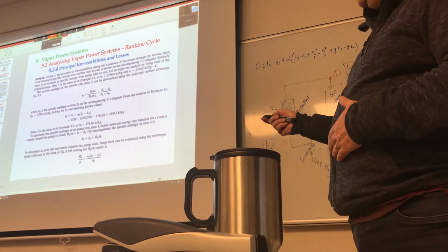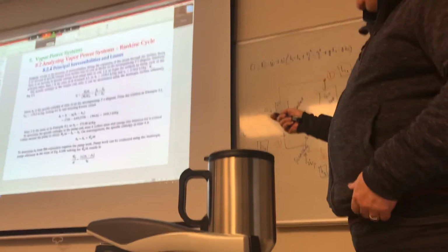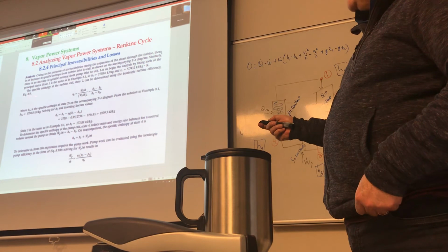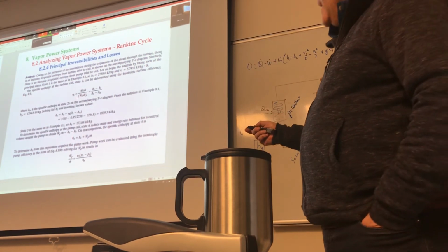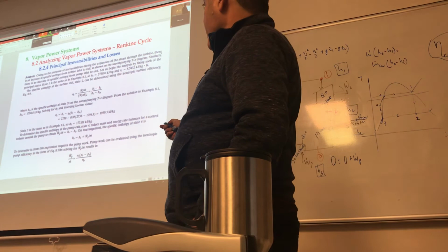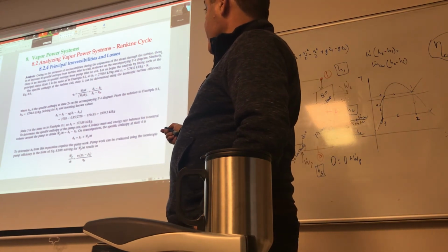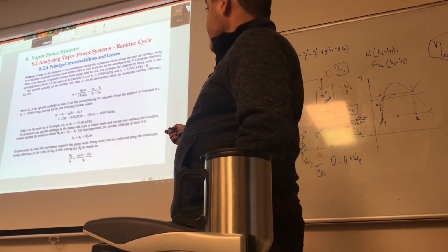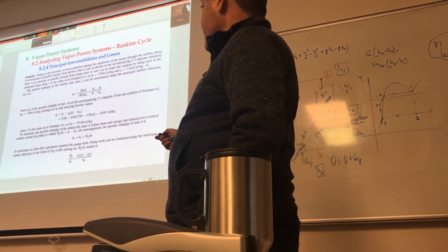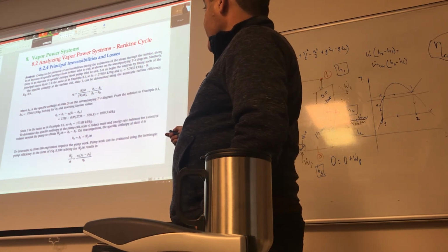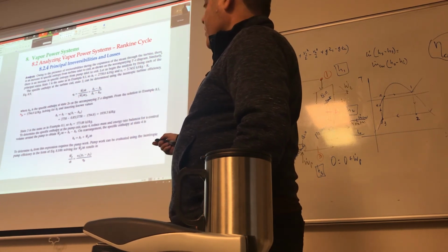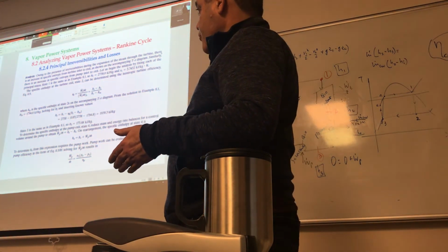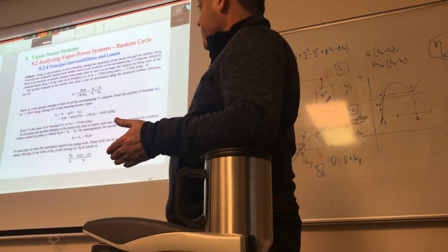The specific enthalpy at state 2 can be determined using the isentropic efficiency, equation 8-9, and therefore eta T is equal to H1 minus H2 divided by H1 minus H2S. Remember that H1 is already known. H2S is the specific enthalpy of state 2 on the TS diagram, which from the example, assuming isentropic, is 1791 that we get from the previous table.